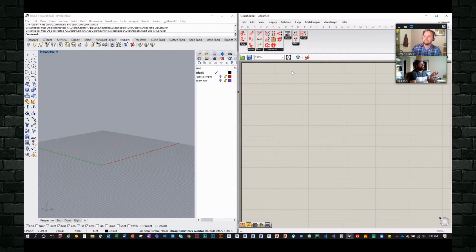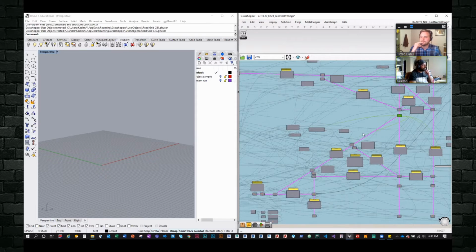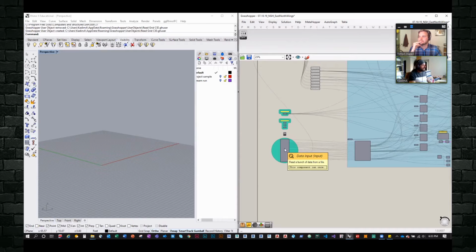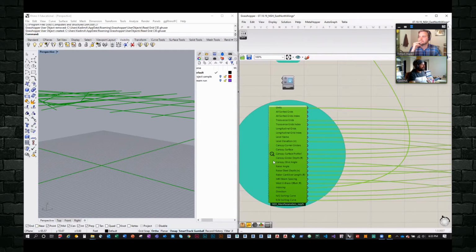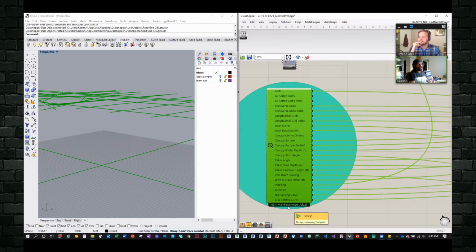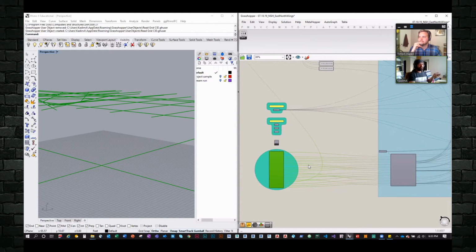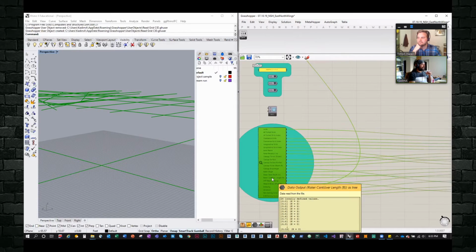The other thing that I've also done is, if you notice in my original stream, these are all the clusters, but my initial parameters are coming in from the outside. So this is referencing a data file. That's because this stadium, from the script, generated like 2,400 steel members with all their properties, like section profile properties, and sometimes some of them had releases. So it was difficult to combine everything in just one file.